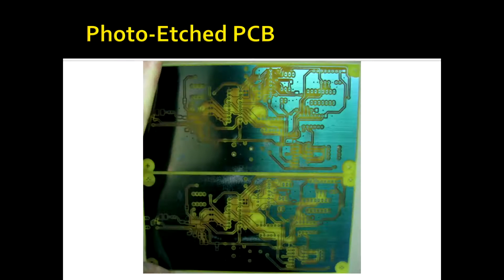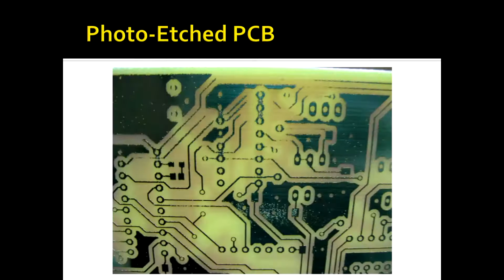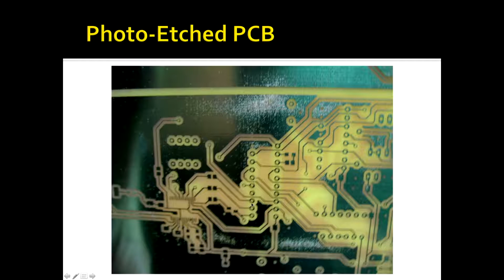So basically I had blurred pads and traces that didn't develop properly, so you can see stuff like this probably isn't conducting too much current. Sections right here were wiped out entirely, and you can see the ground plane is starting to get attacked, because you leave it in there to try and eat through some areas, and meanwhile it's starting to eat through areas you want to stay there. Here's another example of that.